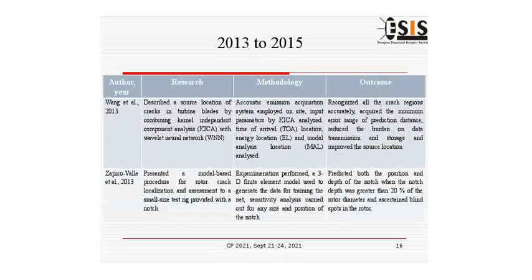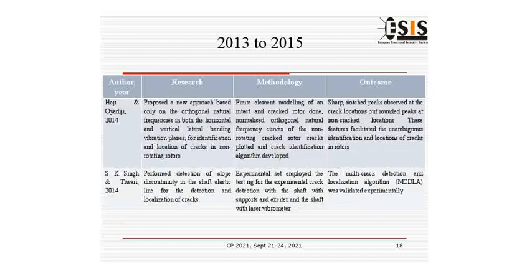Zapico-Vallée et al. presented a model-based procedure for rotor crack localization and assessment to a small-sized test rig provided with a notch. They predicted both the position and the depth of the notch when the notch depth was greater than 20% of the rotor diameter and ascertained blind spots in the rotor. Haji and Oyadiji proposed a new approach based only on the orthogonal natural frequencies in both the horizontal and vertical lateral bending vibration planes for identification and location of cracks in non-rotating rotors.